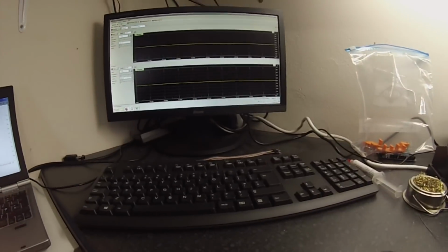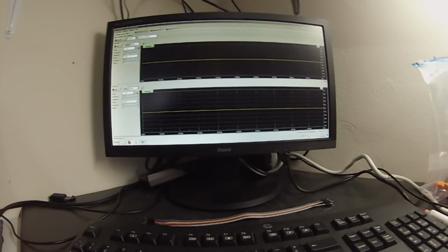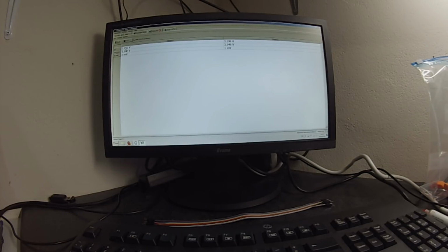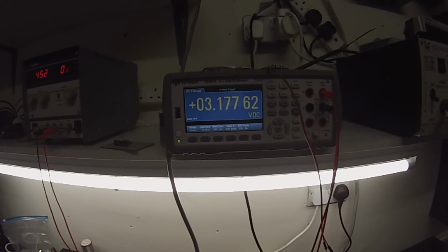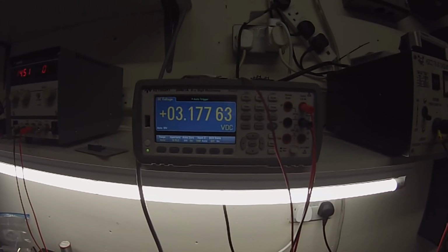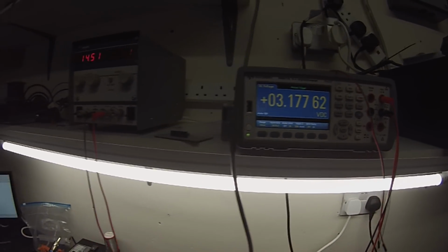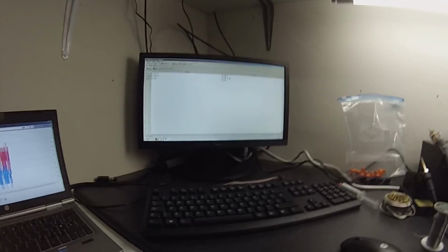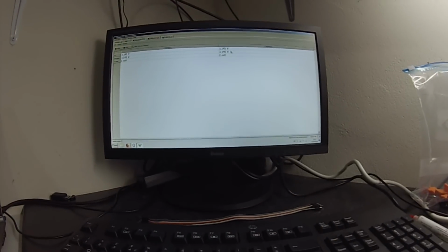Now, at this point, if we look at our voltmeter output from the signal conditioning circuit, 3.14 volts per channel. As you will see here, that is just below our 3.17 volts for our high end of the window comparator, and thus our inverter works away quite happily.